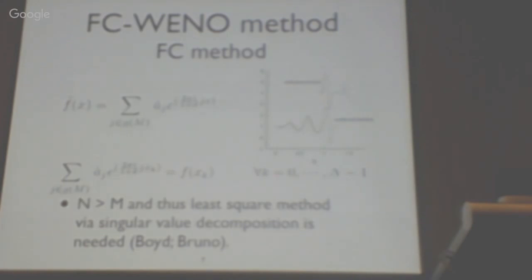And if I may, do you see any issues going to unstructured grids? Okay, so if you're going to tetrahedra, I haven't figured out how to do it. But if you go with structured hexes that are deformed, yes, it is doable, because you can do it through a mapping.